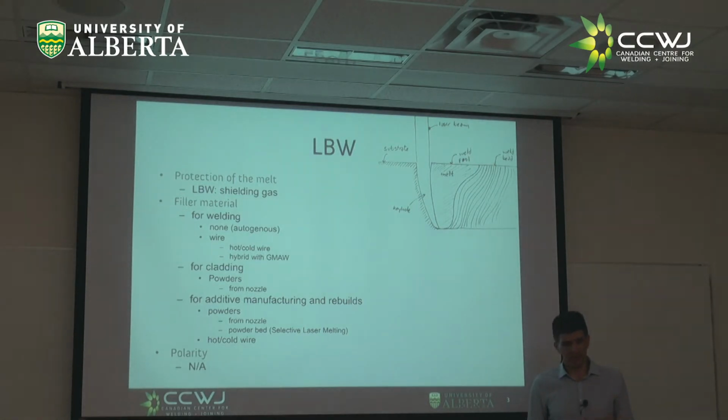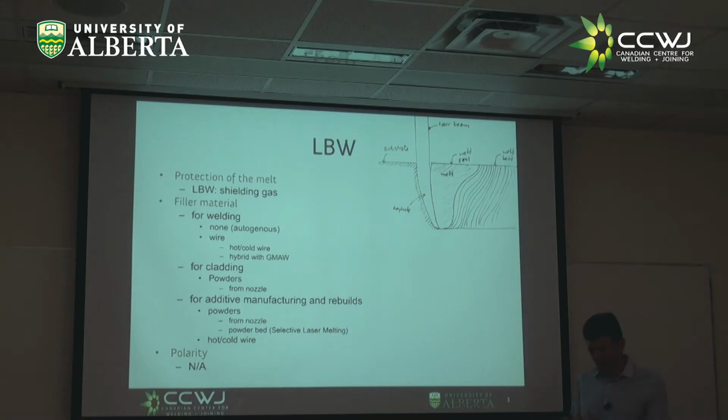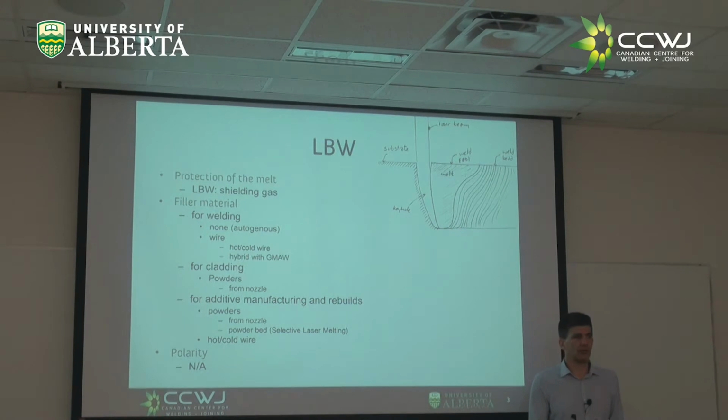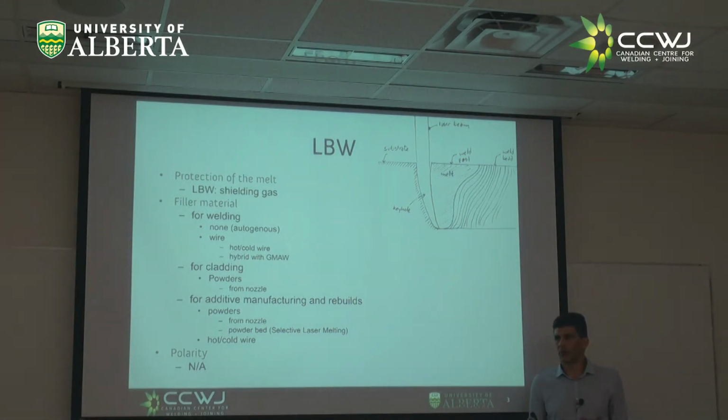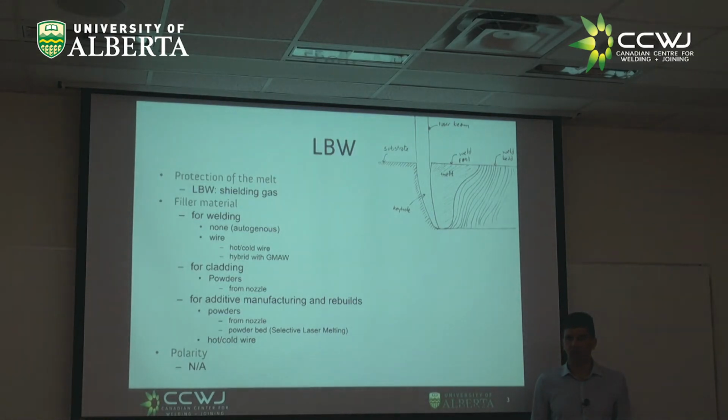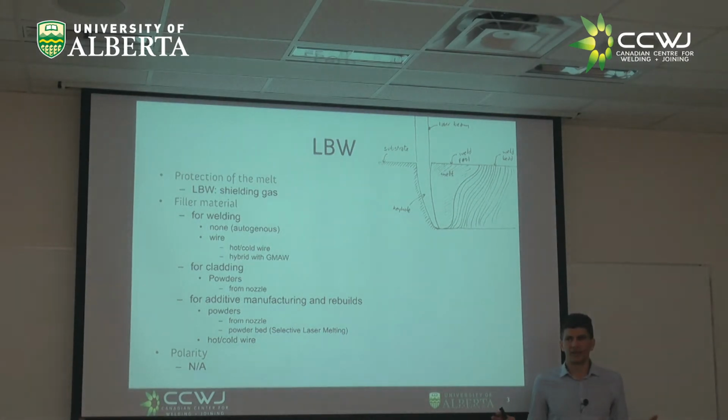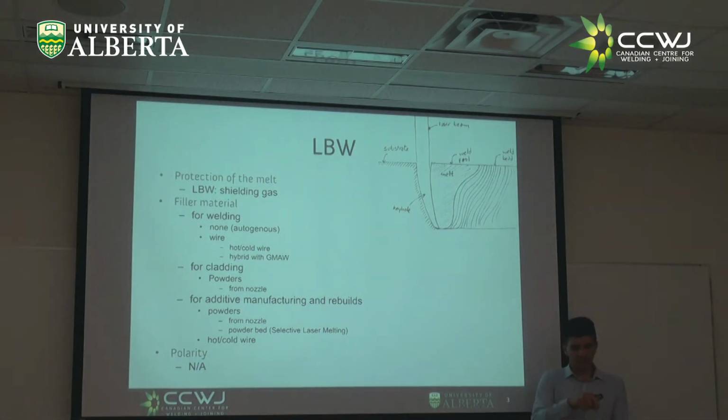If you haven't seen it, I'll show it to you. We're in the process of mounting it. We're going to do that type of things, right? We're ready to do this cladding, right? By blowing powders. And also, a close associate of this laser cladding is additive manufacturing, what is called direct energy deposition. Many of you are working in additive manufacturing, I understand, right? And what they call the directed energy deposition method, right? It's essentially laser cladding. But instead of making one flat surface, you just keep going and give it shape, right?